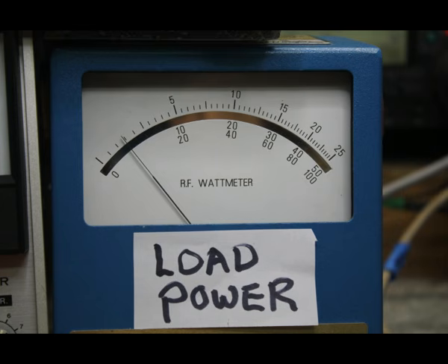We're not consuming too much power in the mismatch tuner, and we wind up with 3 watts of power into the load. We don't want to put too much stock in the exact quantities of power here right now, because all of the meters, except for this final one that's at the load, are running at a pretty high SWR. So they're at the low end of the scale, a long ways from the calibration point where I calibrated the meters.